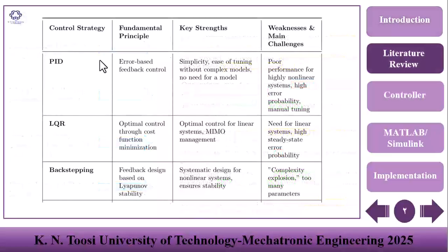Here, we compare some classical control strategies. The PID controller is the most common. It's simple, it's easy to tune, and doesn't require a mathematical model. However, it performs poorly for highly nonlinear systems, has a high probability of error, and needs manual tuning.